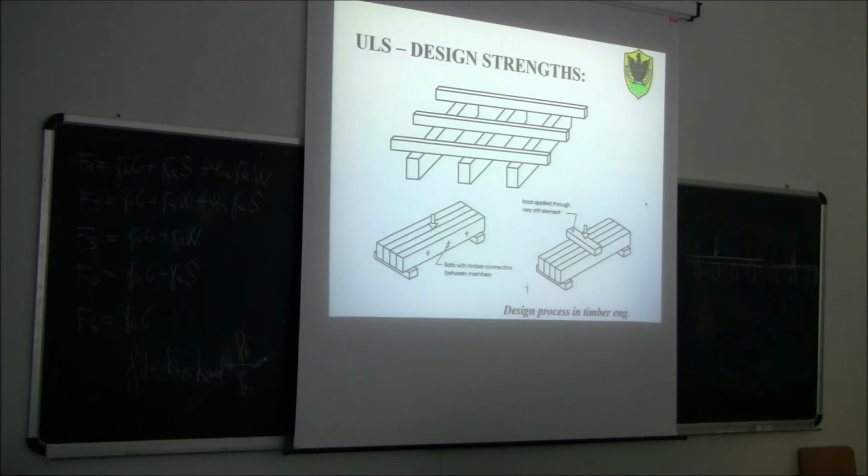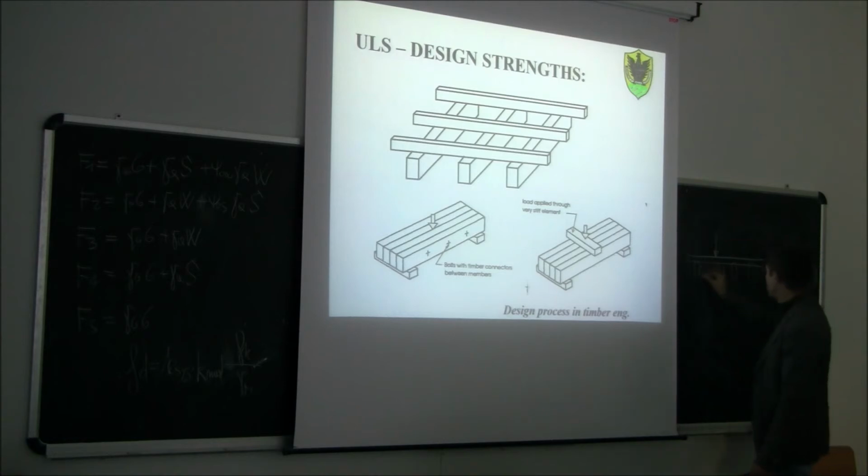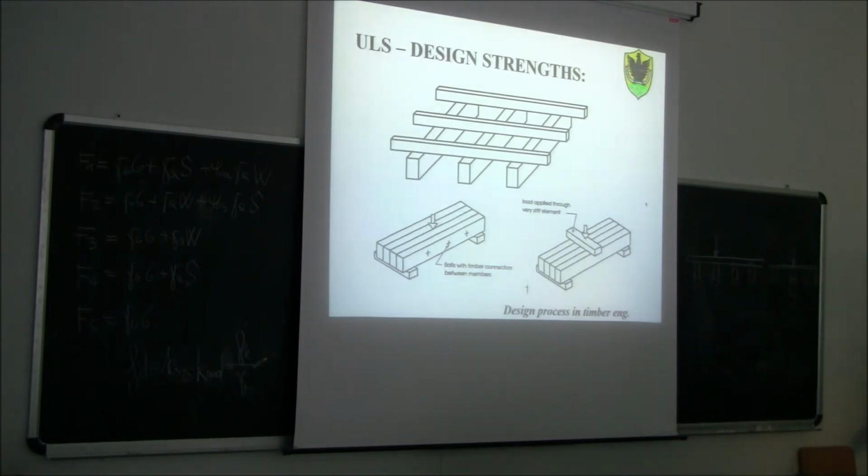The capacity to distribute. Exactly, the capacity to distribute the load here is almost zero. So here you would have, as an effect, a deflection of this beam, and the others would be hardly loaded. While instead here, since you have a strong member, this load is going to be applied on all these beams. So all of them are somehow loaded together. They act basically like a plate on a spring support.